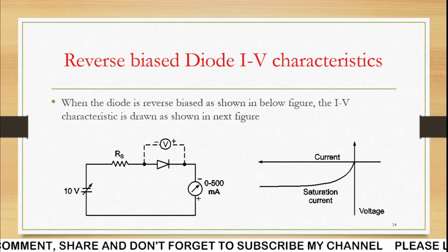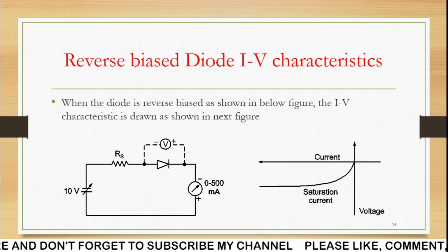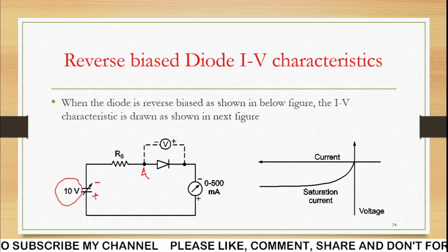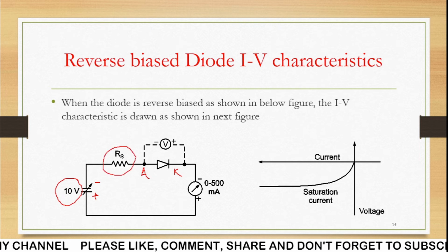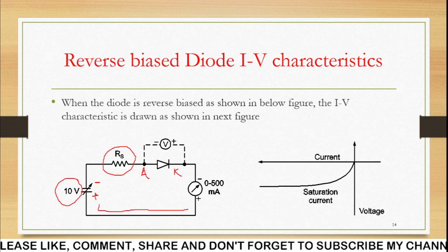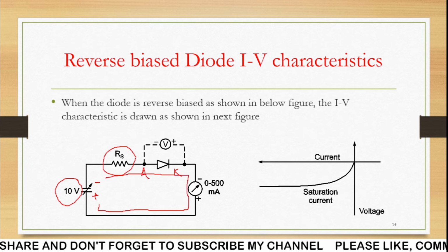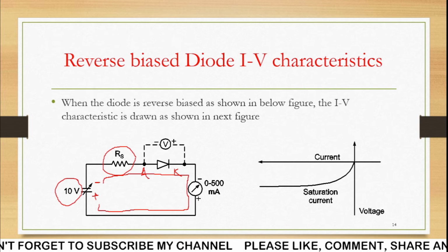Now, in case of a reverse bias characteristic of a diode, you can see here the voltage is of 10 volt and the negative terminal is connected to anode and the positive terminal is connected to cathode. The resistance R is the same as it is, and you are getting the current. So you can see the current will flow from the positive terminal of the battery to this ammeter's positive terminal, then cathode, anode towards the negative terminal of the battery. So you can see the current is flowing in a reverse direction.